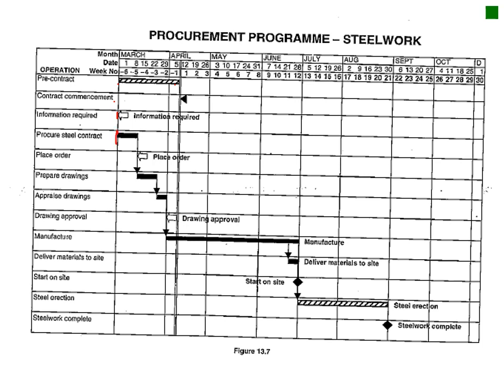So then you sign your contract with your supplier, then you place your order. Okay, so there's the quotation period from the suppliers, subcontractors, etc. Then you place your order over here, and then you prepare your shop drawings, usually appraise the drawings, and then drawing approval, so it's approved, and your materials ordered.